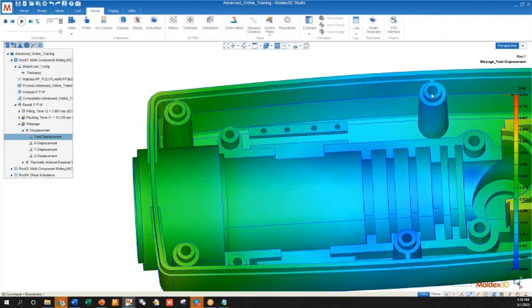But more importantly, it tells us the difference between the modeled distance and the post-warpage distance. This allows us to predict, by comparing this to maybe a spec sheet or a parameter sheet or a tolerance, whether our part is acceptable or not.